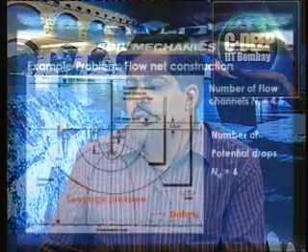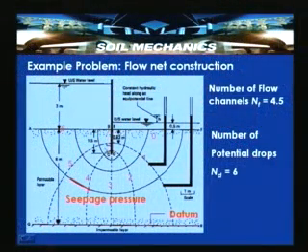Now, if you look into this, this is the first flow channel, and this being a flow line, the water creeps along the boundaries. So, you can see that this is the first flow line, and then the equipotential line is constructed dropping perpendicular from here and from here and from here, seeing that the curvilinear squares are achieved. Then 1, 2, 3, 4.